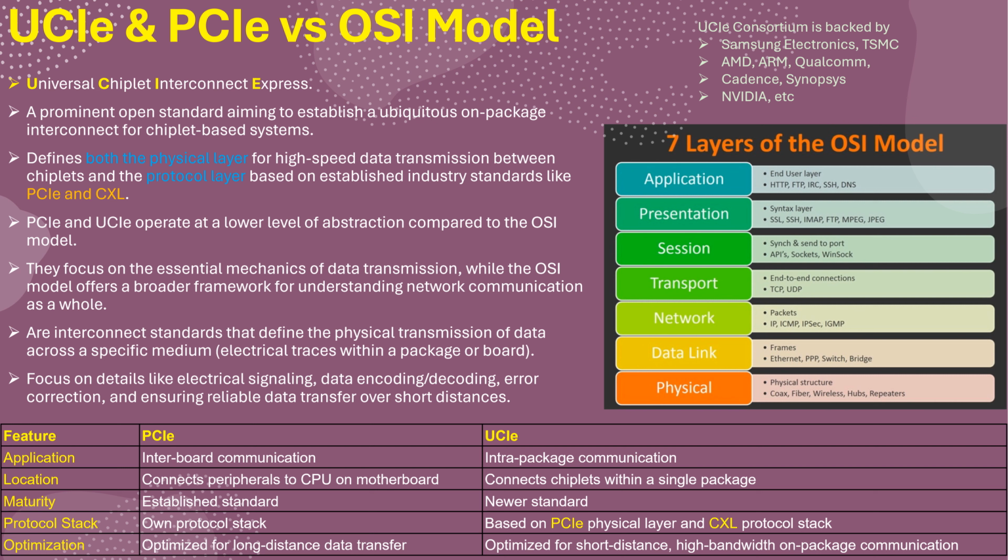UCIe is a relatively new standard, and it's based on the PCIe physical layer and CXL protocol stack. UCIe is optimized for short distance, high bandwidth on-package communication.